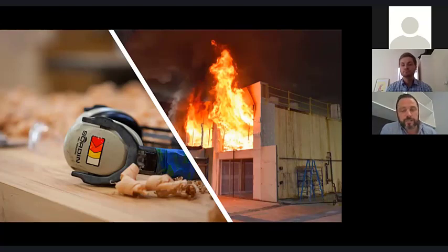Soffit would mean that you'd need to build up above, but there are some pretty good composite timber concrete solutions coming out on the market now that allow a screed to be poured over the top. It improves the structural performance, allows it to span further, and maybe can open up the opportunity for post and beam solutions. With that concrete, you're also resolving some fire issues, as well as acoustics, and allowing you to expose the soffit. So it's definitely not saying you can't expose them. I think that's where the next step of the evolution of this design goes.